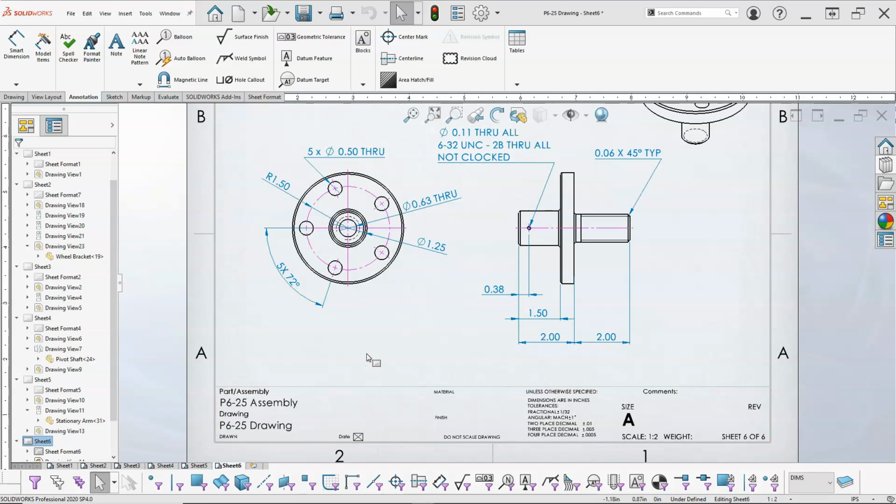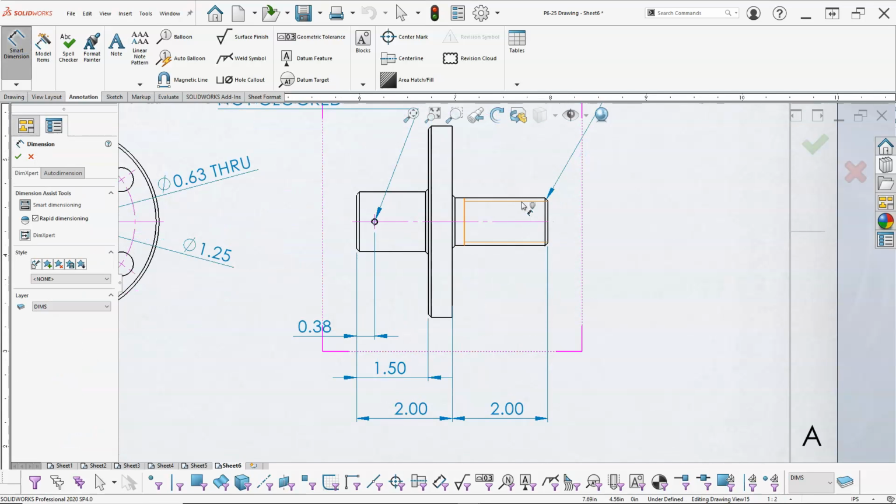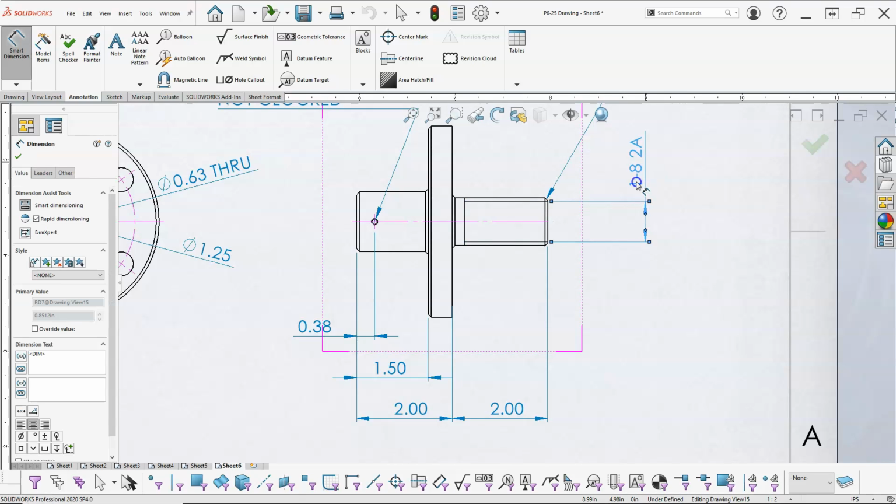We've made several iterations through this drawing in the assembly. One of the things that would probably be helpful here is to put the thread. So if I go between the two cosmetic threads, I can get the 1/8 or 1" 8 2A, and that just goes back to the dim that was called out in the cosmetic thread. And let's go add the to a depth of 1.75, and that will complete that out.